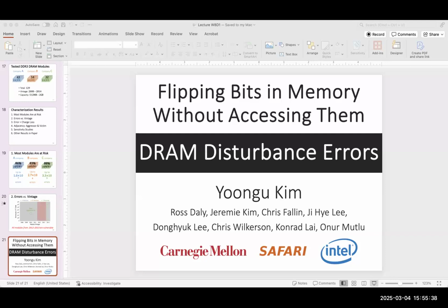But according to this coding, 2.49 is what? Logic 0, which it should not be, because we were outputting logic 1. So it should also be logic 1. But since we are saying anything less than 2.5 will be treated as a logic 0, this is known as a disturbance. If a disturbance happens, we can have a bit flip. So actually what is happening here is your bit is flipping from the logic 1 value to the logic 0 value. Okay.